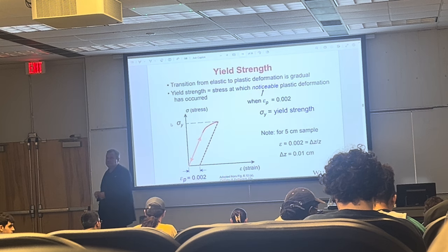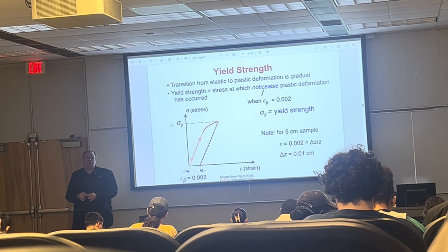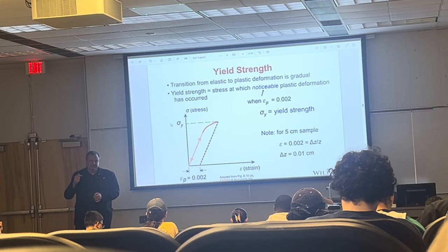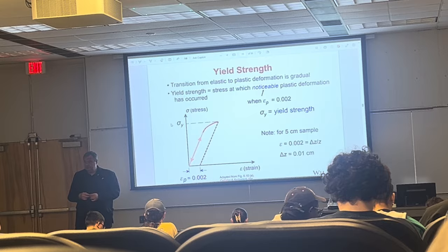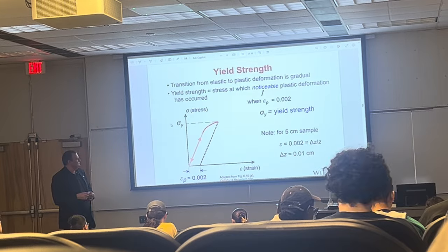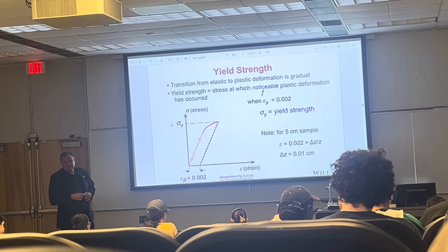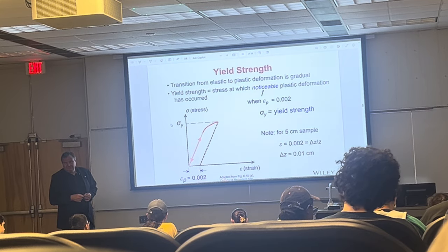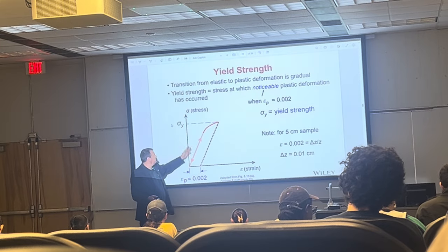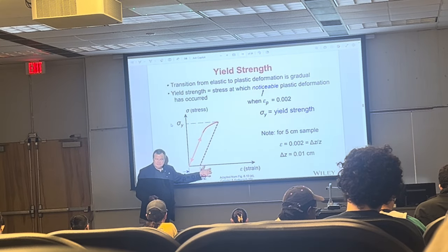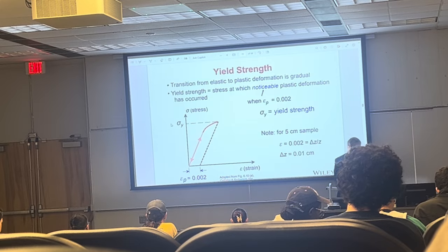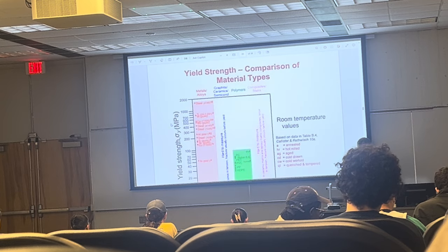So the yield point, or yield stress, or yield strength, meaning the same thing, is a data point on the stress strain curve. And it has the units of pressure, pascals. And also the elastic modulus, which is this slope, has the units of pressure, pascals, because this is in pascals and this has no units. Two parameters, two properties for a metal: elastic modulus and yield strength.